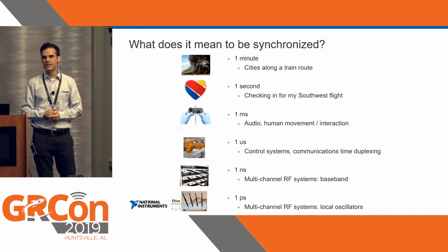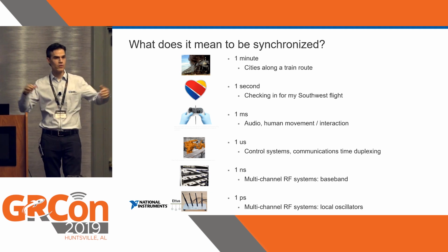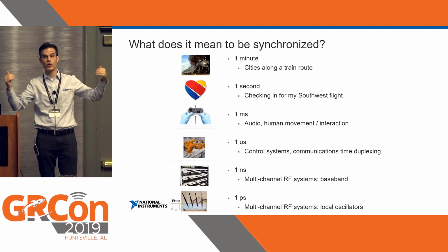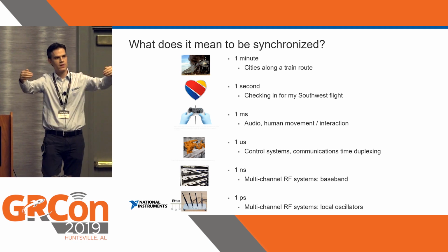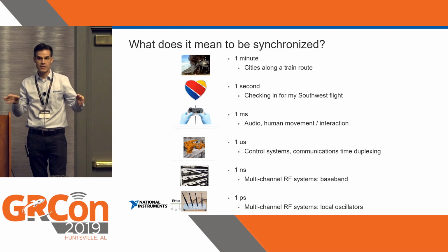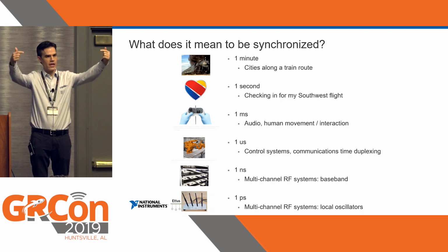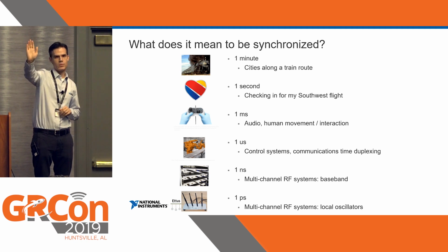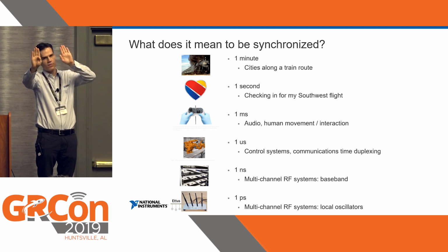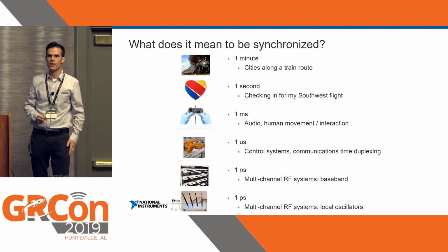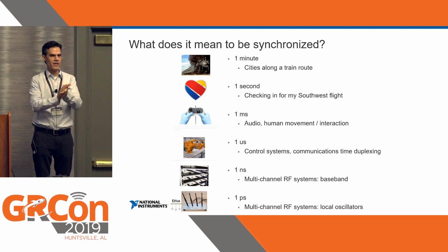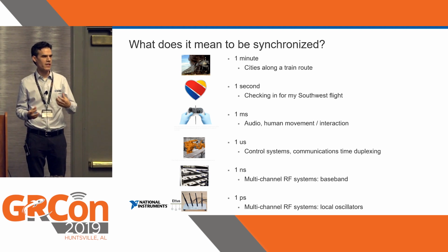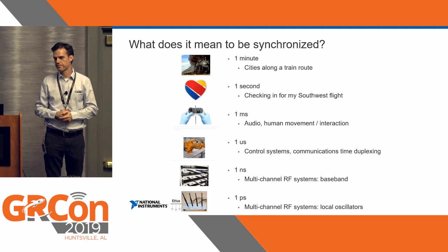A millisecond is detectable in audio. So think about it. You go to one of these huge stadium events, and they've got the big speakers in the front, right? But then as you go further back in the stadium, there's a second rank of speakers and then a third rank of speakers. And they delay the electrical signals going to the second and third ranks such that the audio coming out of the speakers in the back of the room lines up with the wavefront that was coming from the front of the stadium. And if you get that off by more than a millisecond, you'll hear the double click, right? You'll hear the double beat of that. But if it's within a millisecond, you probably won't ever notice, right?